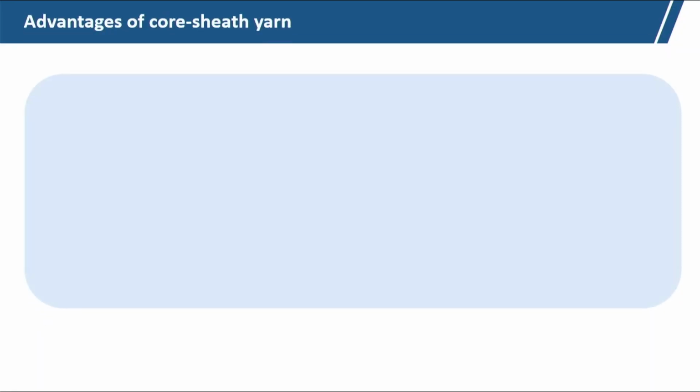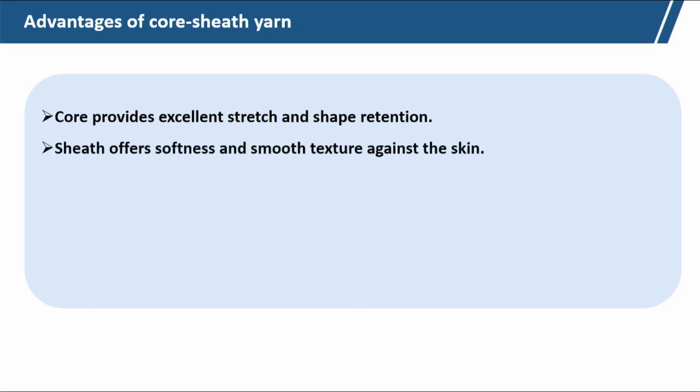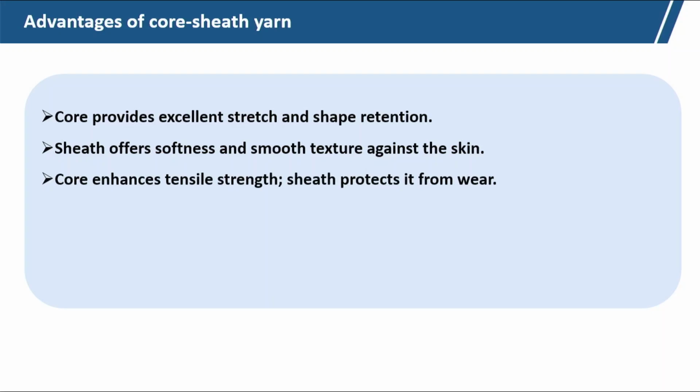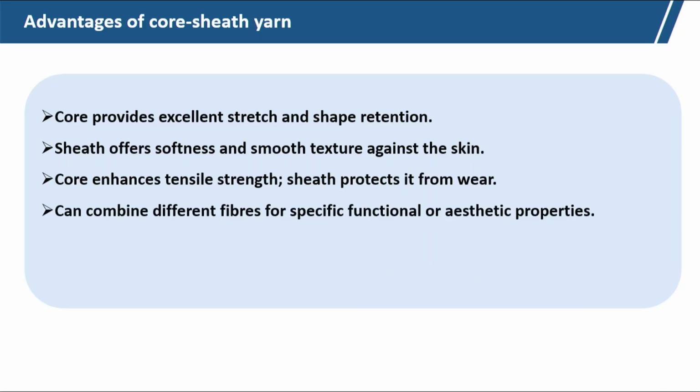So, advantages of core sheath yarn: core provides excellent stretch and shape retention. Sheath offers smoothness and softness, gives a better feel. Core enhances the tensile strength and stretch. It can combine different types of fiber for specific function or aesthetic properties.